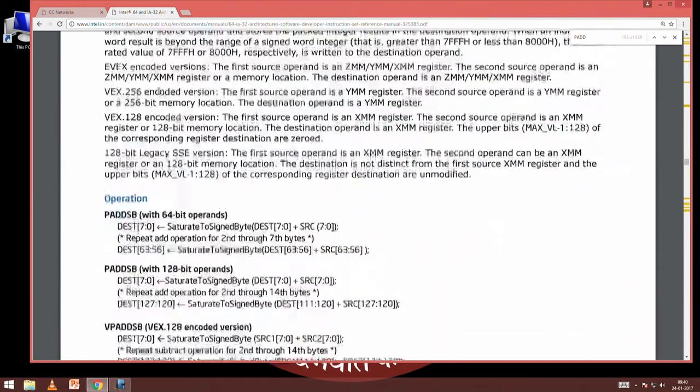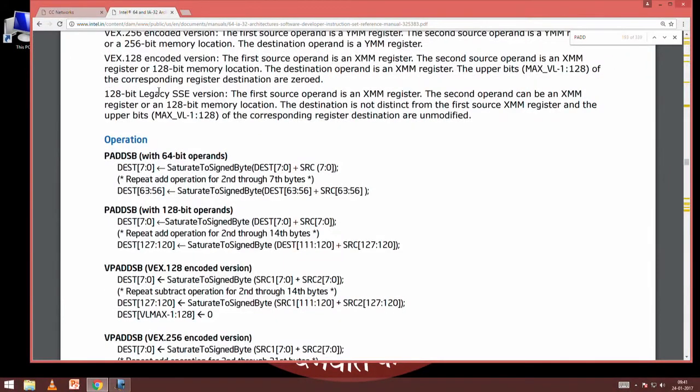Let us go at one of these. So I have a 64-bit operand. This will split this 64-bit operand into 8 bytes, so it will have 8 such operations. I will have 2 registers of size 64-bit, each with 8 bytes. I will split that 64-bit register into 8 bytes, and another 64-bit also into 8 bytes, and I will do the same operation, like I will add the respective bytes here, right? You understand this? So this is PADD with a lot of variants.